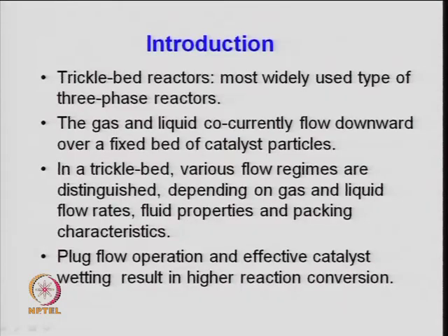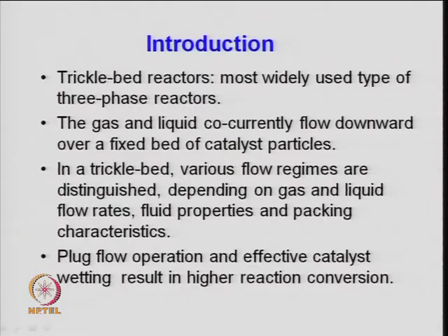So, that is again important, and that will depend on the gas and liquid flow rate, as I said before, and properties of the gas and liquid. So, it will depend on the viscosity, it will depend on the surface tension, and hydrodynamic parameters are very important. So, the pressure drop needs to be checked, right. So, it will depend on the wettability and holdups, that is gas holdup and liquid holdup, that is the volume of liquid which is inside the reactor per unit volume of the bed, right. So, that is again important, and the packing characteristics.